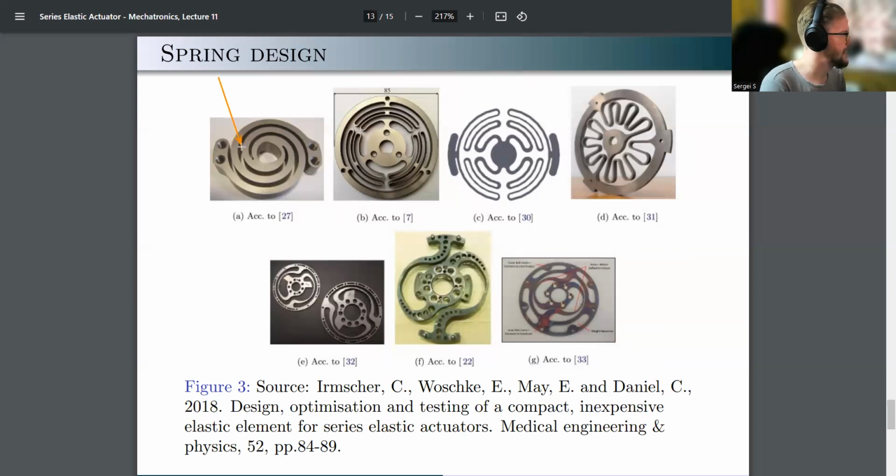You can imagine, this looks stiff because the metal is so big, right? This, on the other hand, looks very compliant. This looks even more compliant. This looks super compliant. This again looks stiff, but since it is very flat, the inertia is probably small, which is nice. Here inertia looks extremely high. This looks like it would have inertia, but because of those small holes, the stiffness will be less, and the inertia maybe a little bit less.